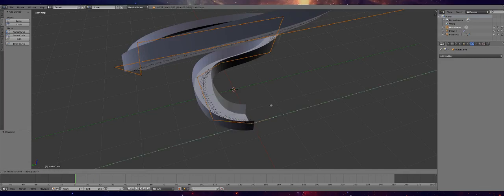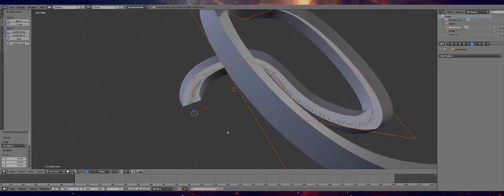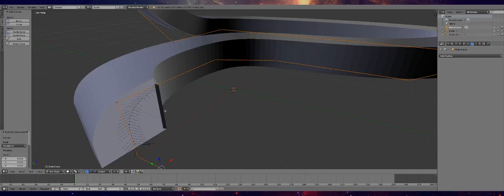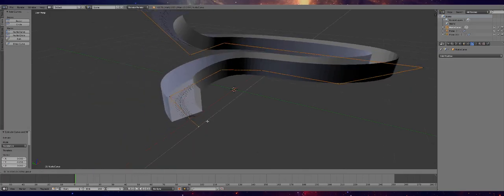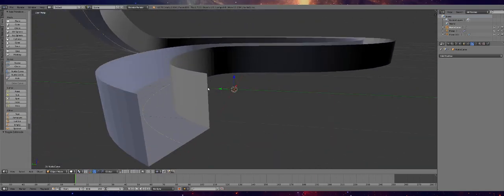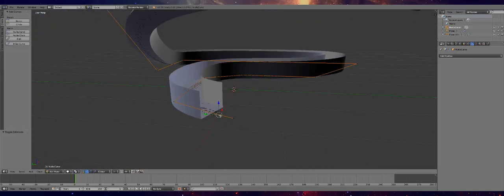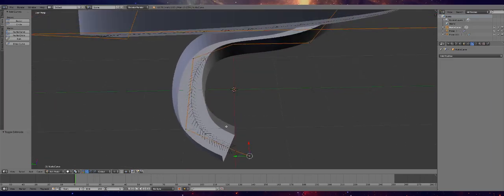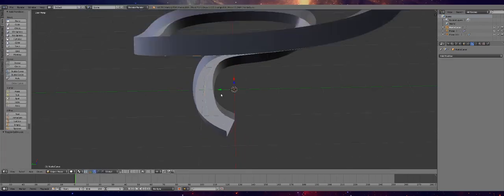So what I'm gonna do is create a new control point, and you can see, hey, that's still messed up, right? But if you rotate, you don't even notice it's not there anymore because this is an extra point and it fits the same direction, so it's not something awkward. That's how you make the end of the track smooth.